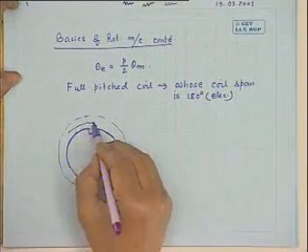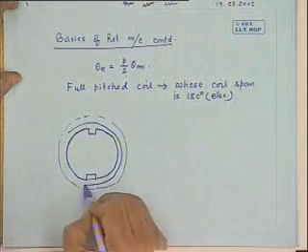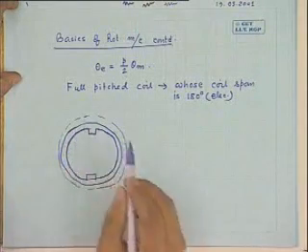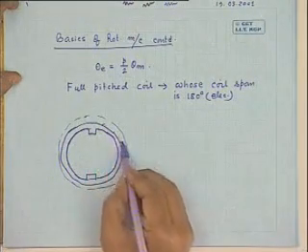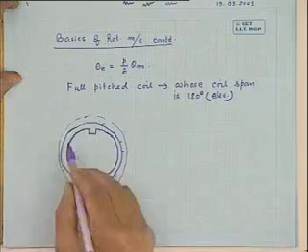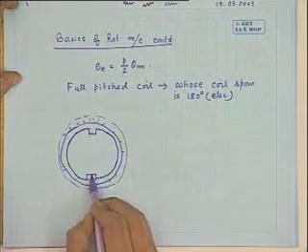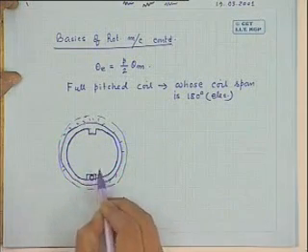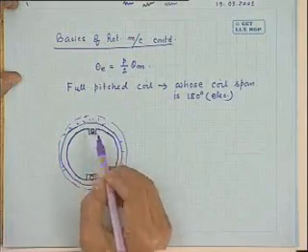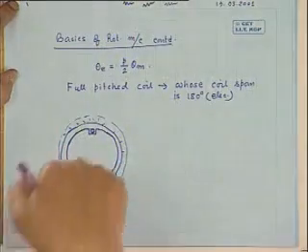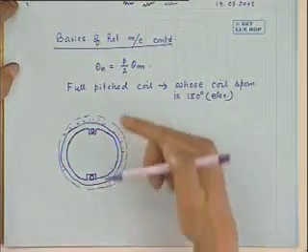This is the stator, where there are no slots. It is only iron. On the rotor, there are two slots diametrically opposite, indicating that it will be a two-pole machine. And there is a coil which goes perpendicular to the plane of the paper. At the end they are joined, and in the forward direction I have got two free terminals, as I told you. Now this coil, suppose it is energized by a direct current.